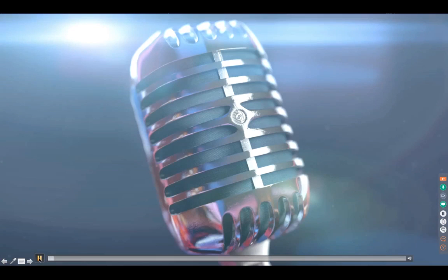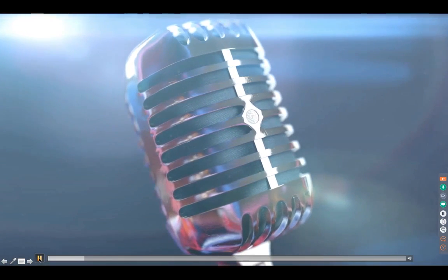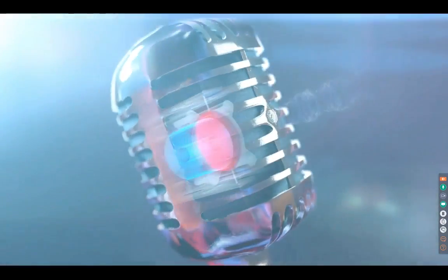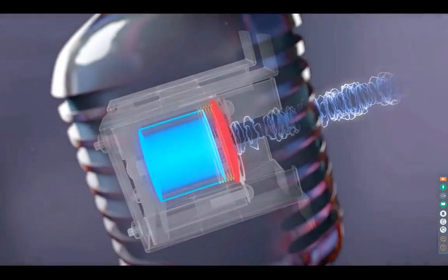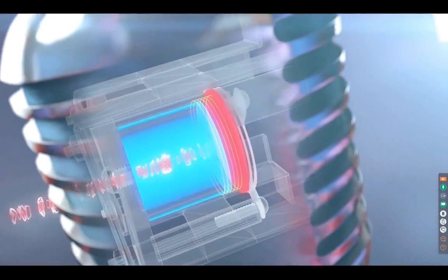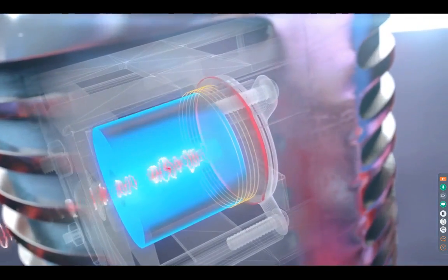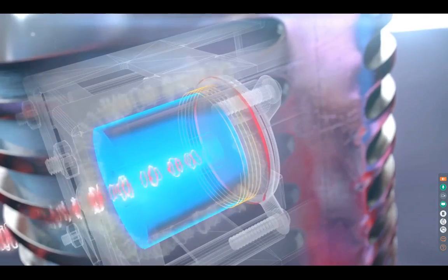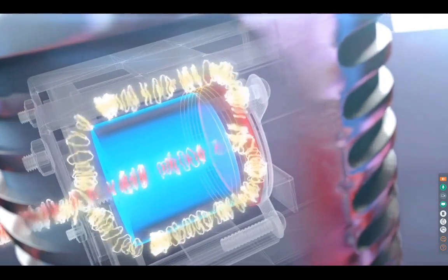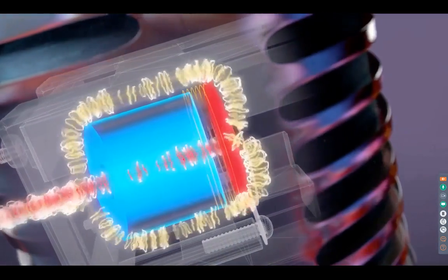Sound comes and strikes the front of the microphone and moves the coil and diaphragm as it would, but sound coming from behind the microphone actually gets delayed a little bit before it strikes the back of the diaphragm. And that delay time is set to the same amount of time it takes sound to actually wrap around the microphone and hit the front of the diaphragm.